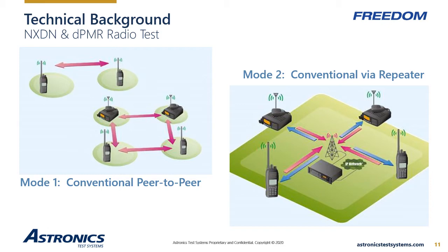The range can be even further extended by linking multiple repeaters together to cover a large geographical area. By connecting the sites by IP using the internet or other private data networks, when a user transmits into the system, the signal is repeated across all sites, potentially anywhere in the world. Each site may have its own frequency pair, but when the repeaters are linked, all pairs are used at the same time for a single conversation.